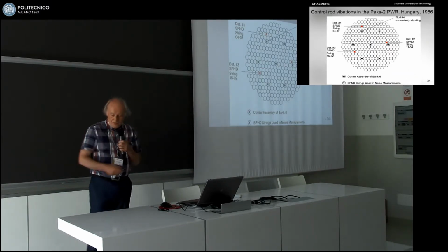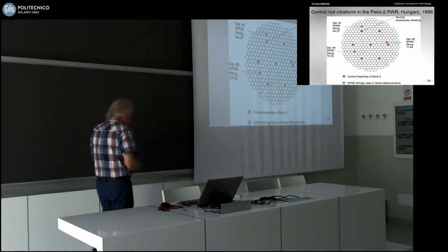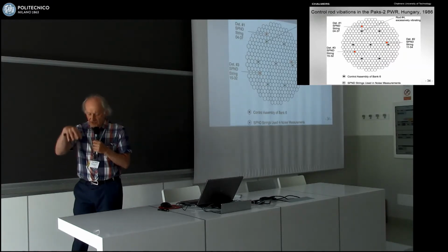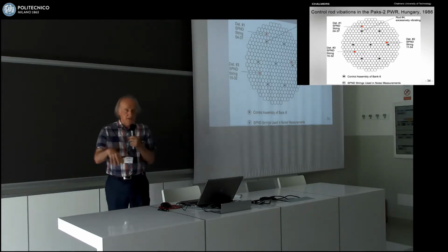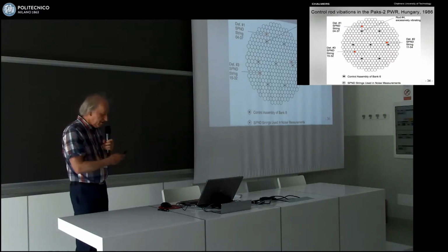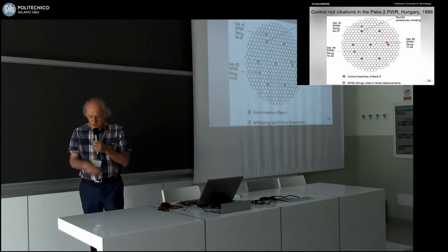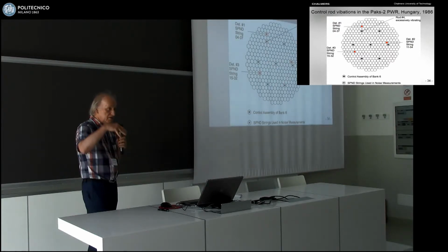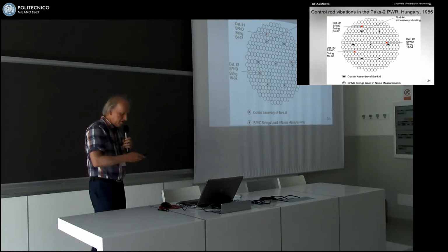This was observed also in, at least, the VVER-440 reactors, which have a control rod that is completely different from the Westinghouse and the others, where the control rods are clusters of absorber pins replacing some fuel elements. In those reactors, like the one in Hungary, it's a big cadmium hexagonal sheet, and that's very vulnerable to vibrations. So that's one case, where one of the control rods of these, the 7 black dots represent the 7 control rods in a bank which can be or were partially inserted into the reactor.